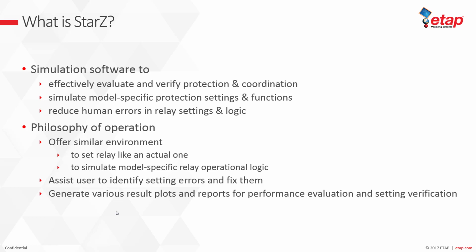Behind the StarZ user interface, there is an intelligent and powerful engine which allows you to simulate and evaluate model-specific protection settings and functions similar to the actual relay.